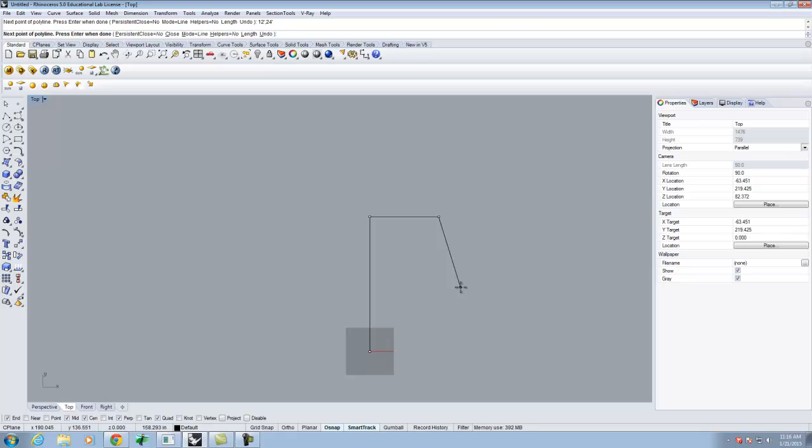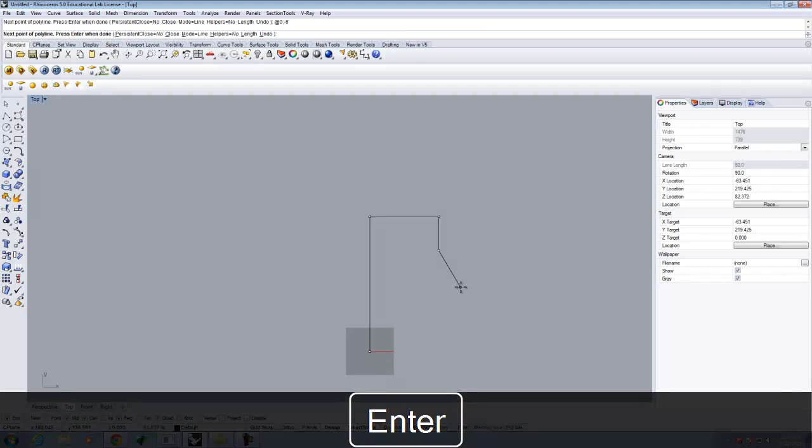So in order to use the relative coordinates, instead of typing numbers, we're going to start with the @ sign, like an email address, the @ sign, and then we're going to type the coordinates. So in this case, we're just going down 6 in the y direction. So it would be 0, 6, or excuse me, -6 feet. Okay? Remember, it has to have that @ sign for it to work. So I'll say at 0, -6 feet, and it's going to go down 6 feet from my last coordinate.